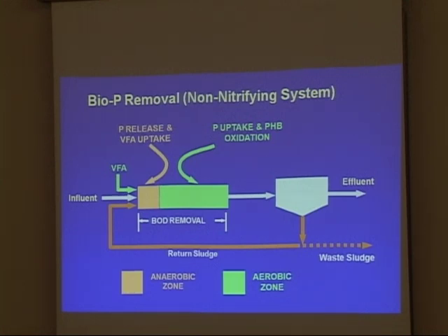If you waste to a DAF unit, which is strictly aerobic, suppose we had a gravity belt thickener, would we get a re-release of phosphorus if we were trying to thicken it with a gravity belt thickener in lieu of a DAF, or would it make no difference whatsoever? It depends how quickly the sludge gets processed, because you can waste directly to a GBT. But if you were storing it for a long period of time before, then that might create the issue, because then it would come out and filtrate.